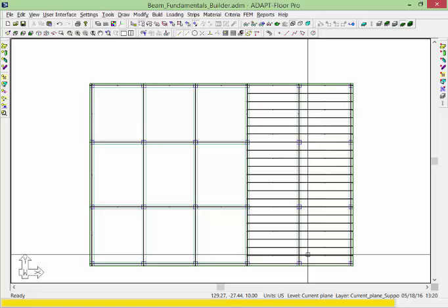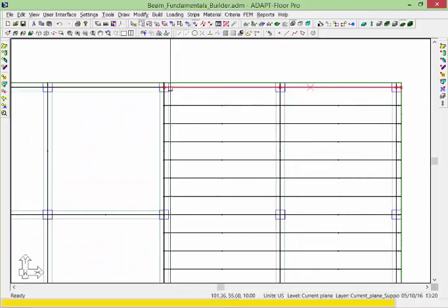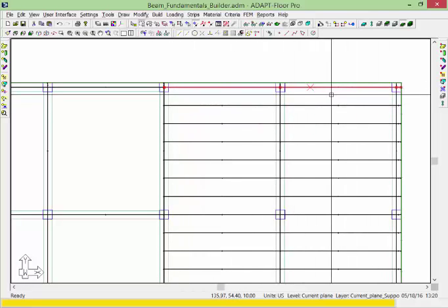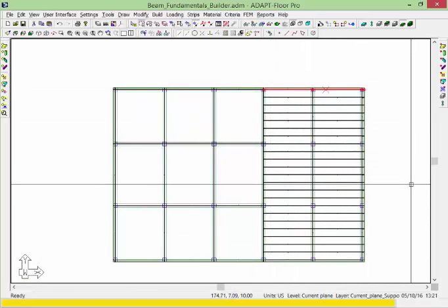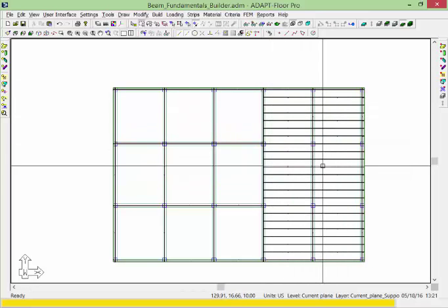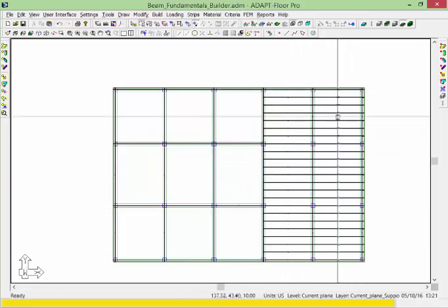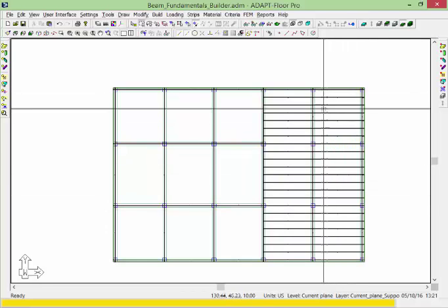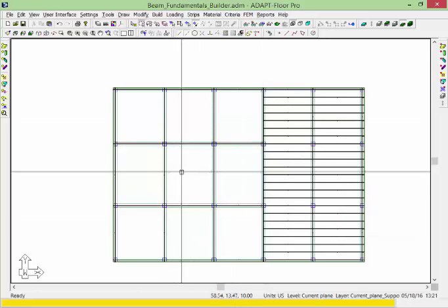If I apply the column middle strip, the program is going to create a middle strip in between each of the already designated one-way slab strips. So you're basically going to get an additional set of support lines in the one-way slab direction, and in addition, in the one-way slab region for the beams, you're going to get a middle strip that's going to cut between the two beams. So you'll have a beam line, a middle strip line, a beam line, a middle strip, and a beam line, which isn't exactly correct in how the one-way slab beam system works. It applies to the left side of the model but not the right.